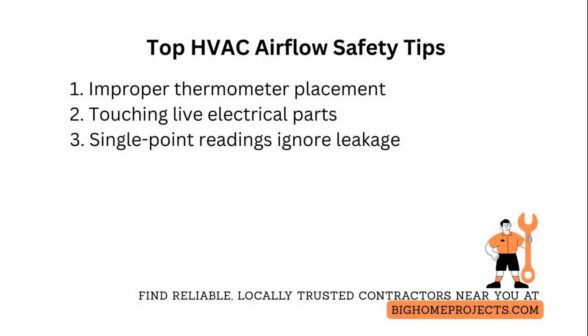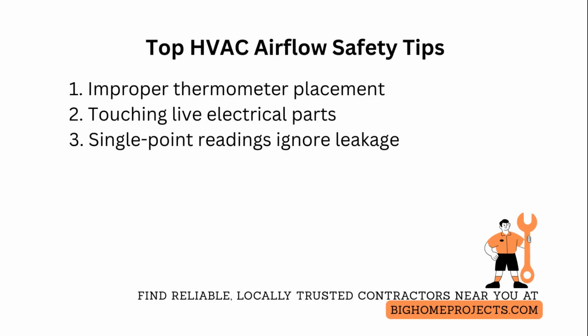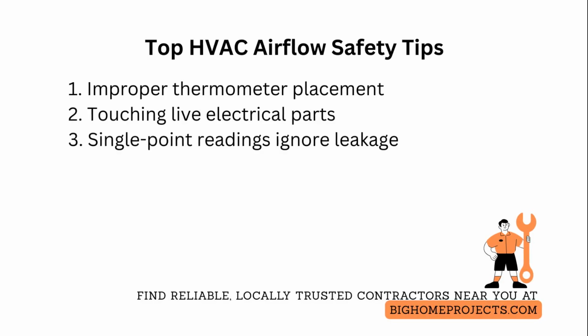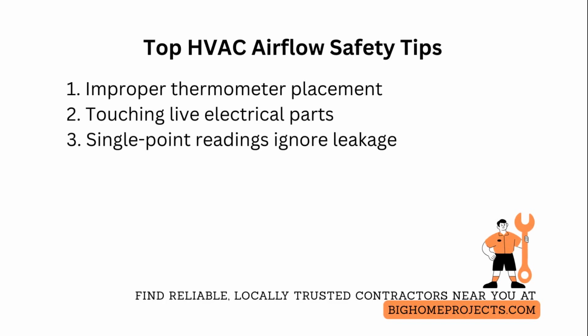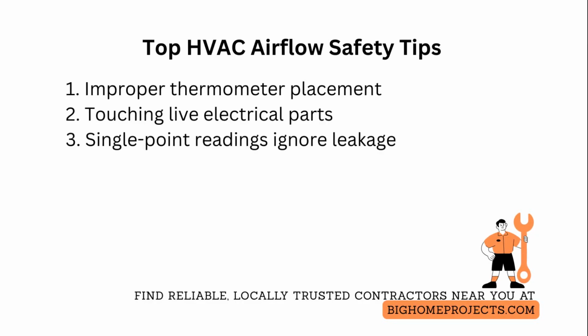One of the next frequent issues is touching live electrical parts while adjusting meters or clamps, linked to HVAC safety during airflow measurement. Avoid that by setting meters and clamp jaws in place before energizing, using insulated alligator clips, and using a non-contact voltage tester to verify de-energized terminals before reaching in.